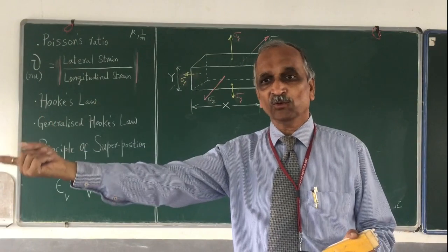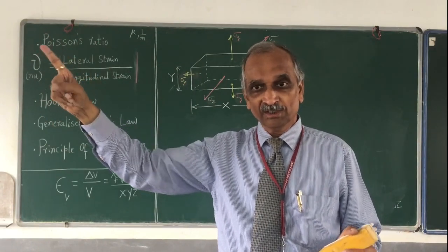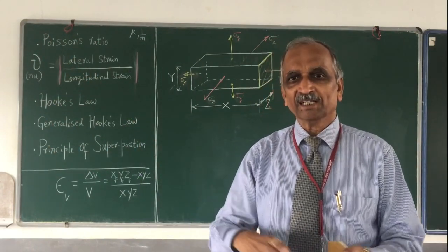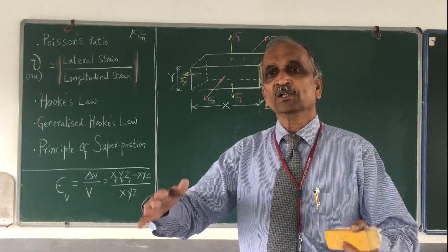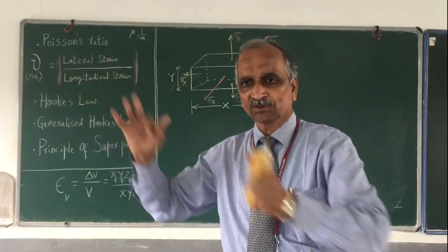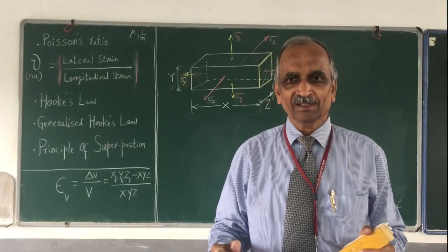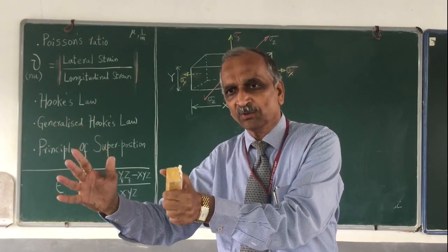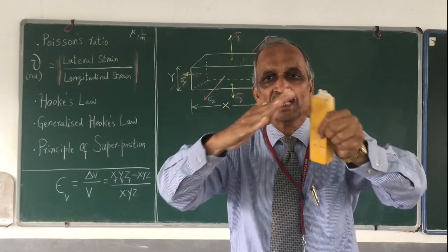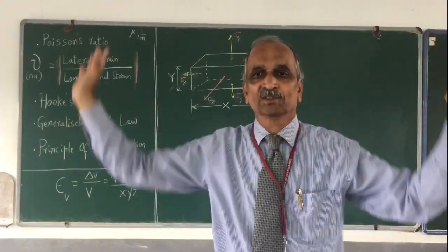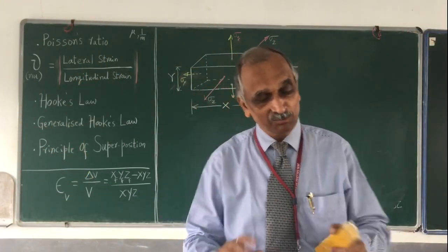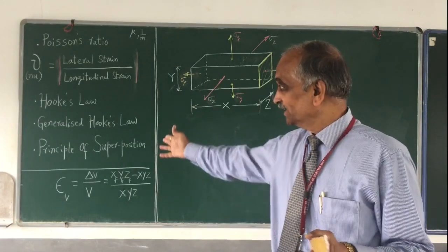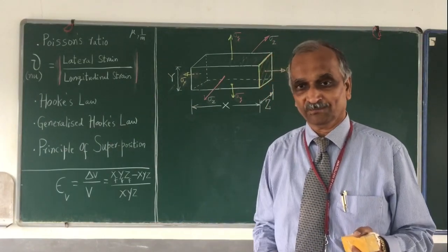Then I take the second force, only one force, and find its effect. Like that I do for all the forces. Then I add the effects due to all the individual forces to get the effect due to all the forces together. Both are one and the same, and that is what is called the principle of superposition.